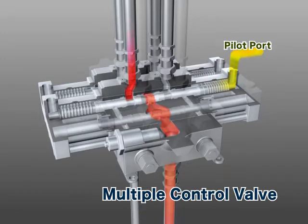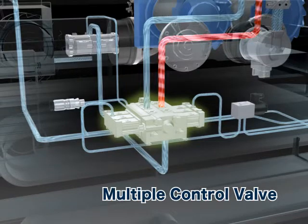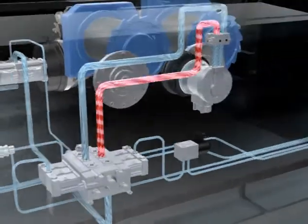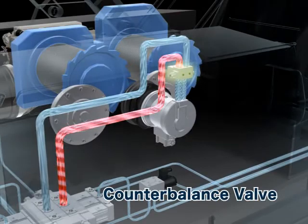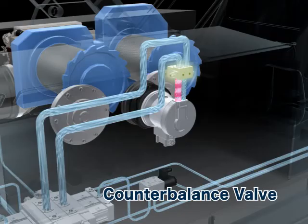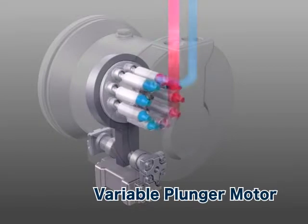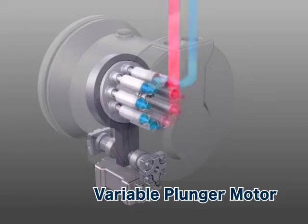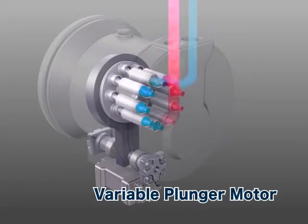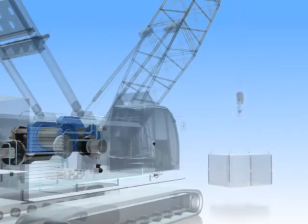Based on the position of the spool, an outlet port is selected and oil is then sent to the variable motor's counterbalance valve. Hydraulic oil passes through the counterbalance valve and heads towards the variable motor, where its pressure then rotates the motor. The drum rotates along with the motor, hoisting or lowering the load.